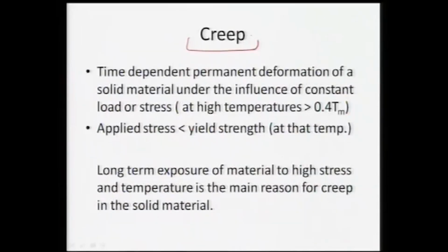Now, coming to another deformation criterion, which is called creep. Creep is a time dependent permanent deformation of a material under the influence of constant load or stress, which is pretty low, much lower than the yield strength, but at pretty high temperatures. Temperatures are ranging greater than 0.4 times the melting temperature of the material. So, creep is a time dependent permanent deformation of a solid material under the influence of load or stress, which is much lower than the yield strength at room temperature, but it occurs at very high temperatures, of the order of greater than 0.4 times the melting temperature.